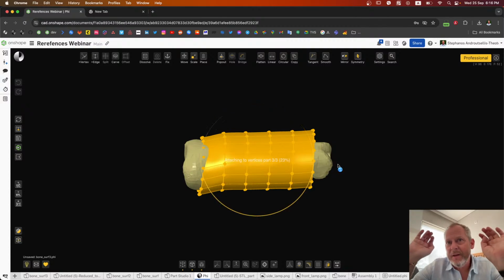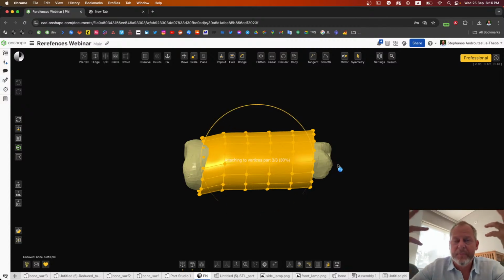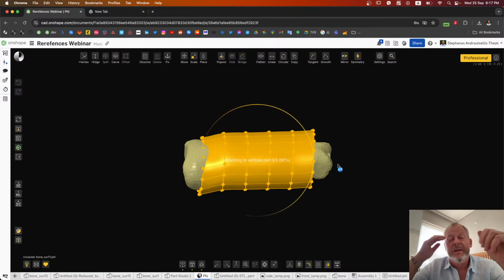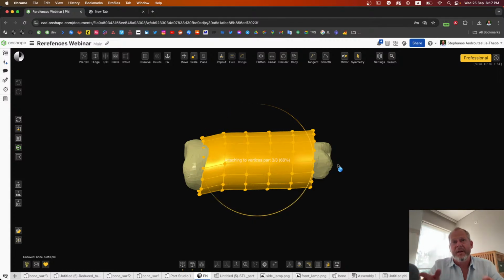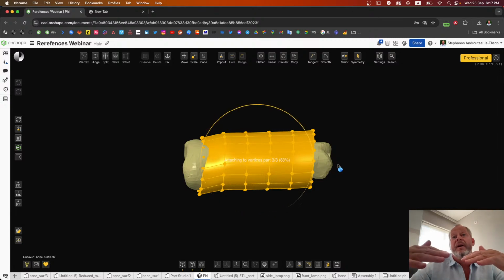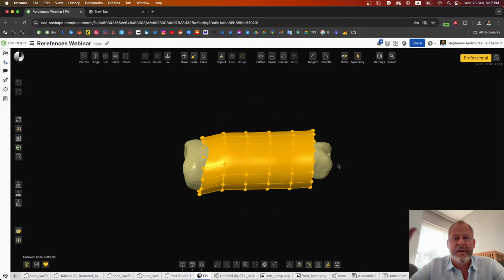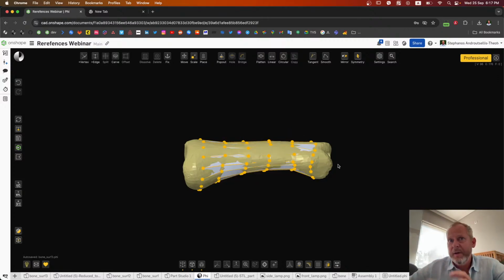Turns out this is not as simple as it sounds, in terms of implementation. You want to avoid protruding STL noise, for example, and have a vertex floating in space. In some cases you may have surfaces that have a ridge, and you don't want to completely miss this feature, so you cannot just go perpendicular towards the center of mass, let's say, of this bone. So it turns out that it's a tricky problem, and we found a way, I think, to give a pretty decent result.